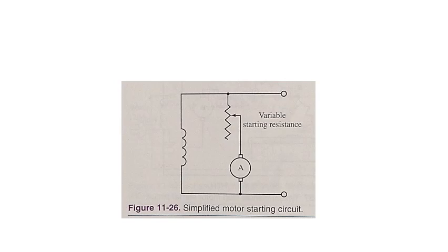Motor starting circuits. Armature resistance in most motors is quite low. When the motor is stopped or at low speed, very little counter EMF is developed to oppose the line voltage. Therefore, dangerously high currents will flow.